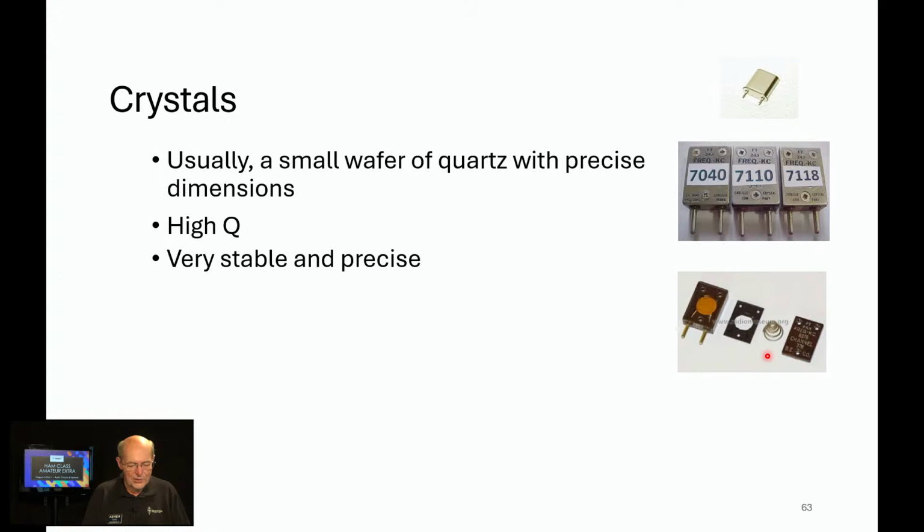And then we'll talk about crystals a little bit. Here's some crystals, and if you were a ham back in the novice days, when it was legal to only use a crystal to control your transmitter frequency, here's some 40-meter crystals shown, some other things. This is the inside of one. A crystal is a piezoelectric device, very high Q, generally over 100, very sharp but very stable, very precise.